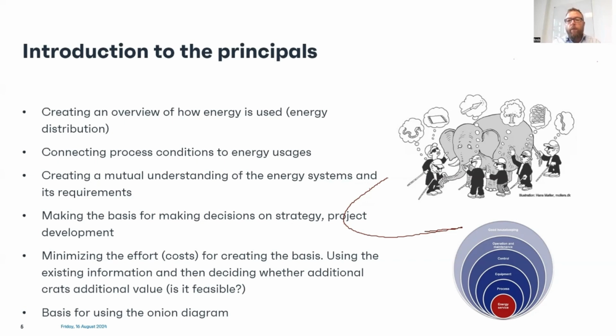So let me give you an example. If you are optimizing your energy service, so reducing the demand for the process, then that will save the energy, of course, for the process itself. It will also save, to some extent, the energy for transporting or distributing the energy from the utility system towards the process, and would also save energy at the utility systems.